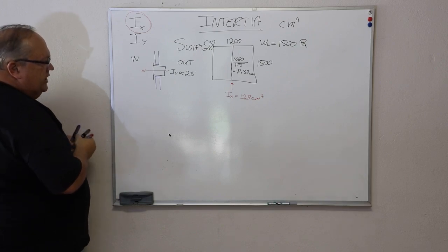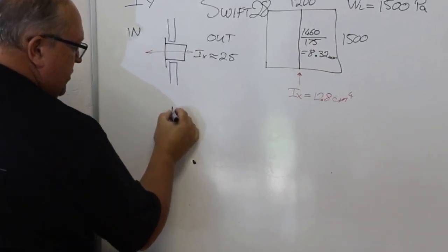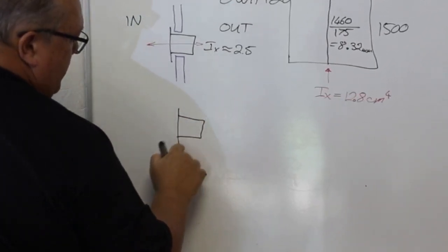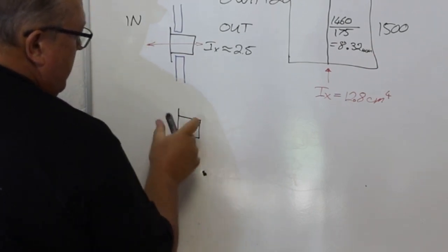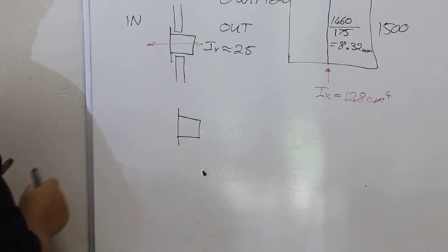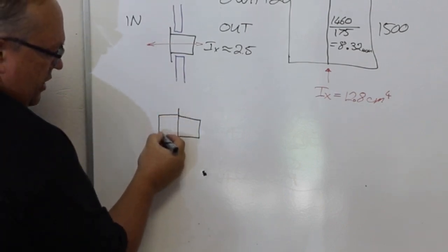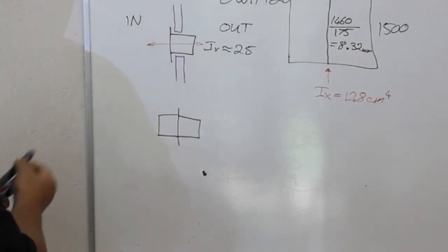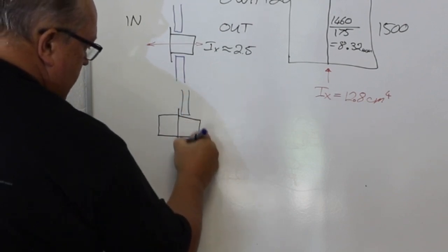If I then looked at, say, a 54 millimeter mullion, so that is your standard Swift 28 mullion, drawn a bit more accurately, this part stays identical as the standard mullion. But what happens is that the mullion now grows towards the inside. I would still have my glass sitting there, my glass sitting here.